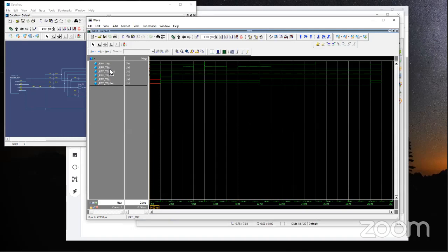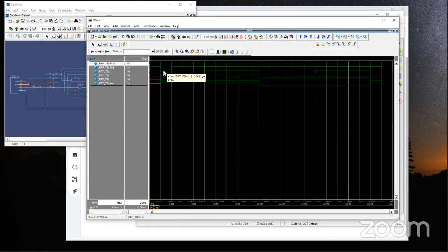But let's see. We are interested in clock and reset and preset, and then we'll see the D and Q in relation to the clock. Look at this preset. I kept it as logic 1. More interesting is the N reset. We give that name in such a way that it implies its operation is on negative logic, which is logic 0.